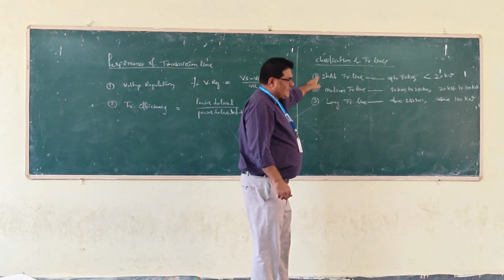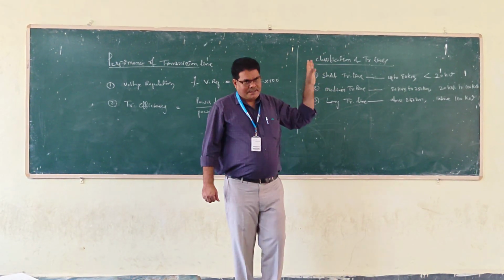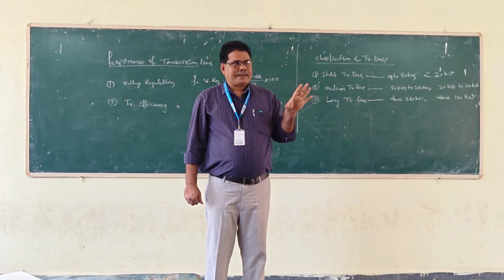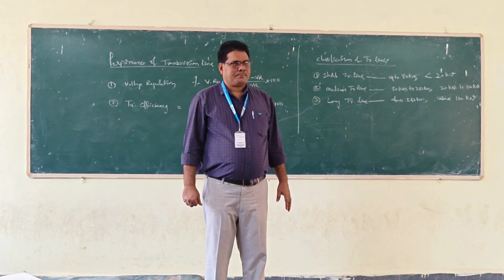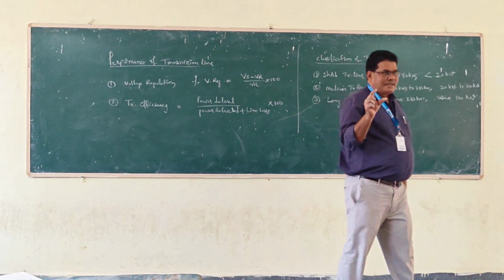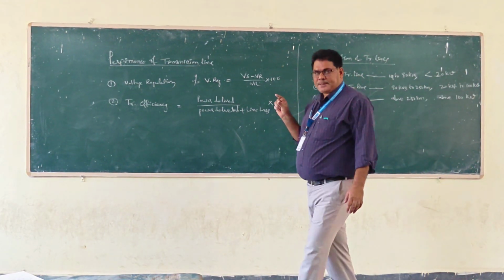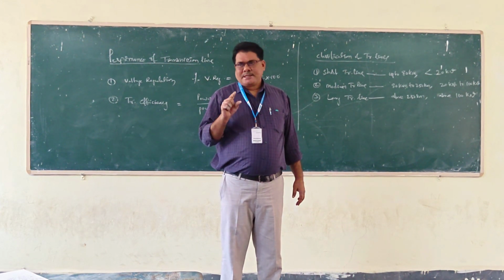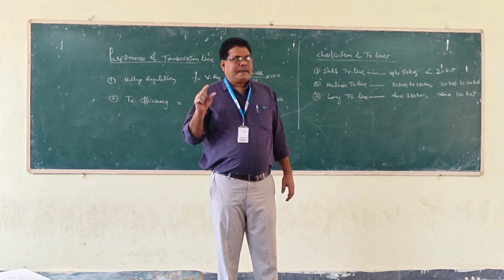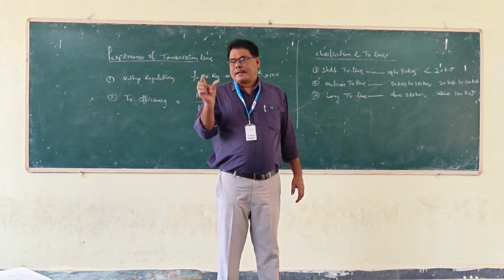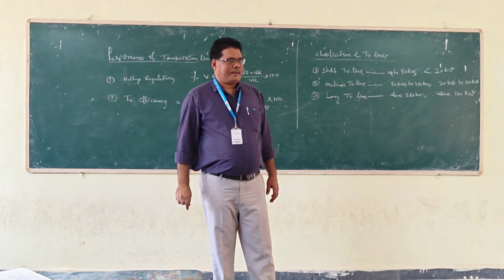So while considering a short transmission line, only resistance and inductance are taken into consideration. Capacitance is neglected. Why? Due to the insufficient length and insufficient voltage, the capacitive charging current is very low. In studying a short transmission line, the capacitance effect is neglected.